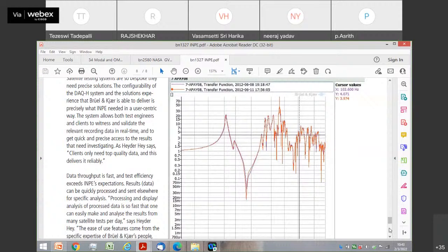If in all 3 directions we are getting the same thing, it means the sensor has a problem. It could be a sensor problem or a DAS problem. I would say check sensor, check cable, check DAS, all 3 independently, because you don't know where the problem is. You put 2 sensors side by side, and then you see what the result is.